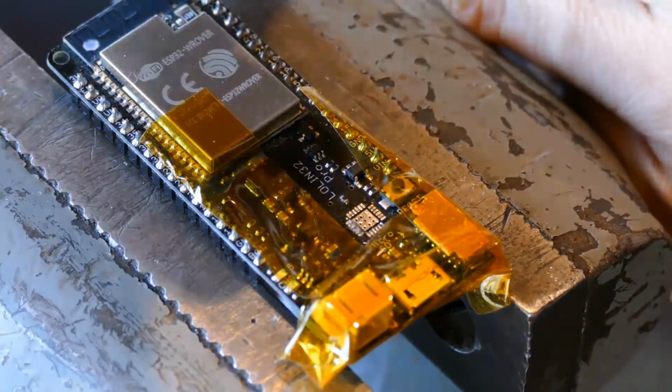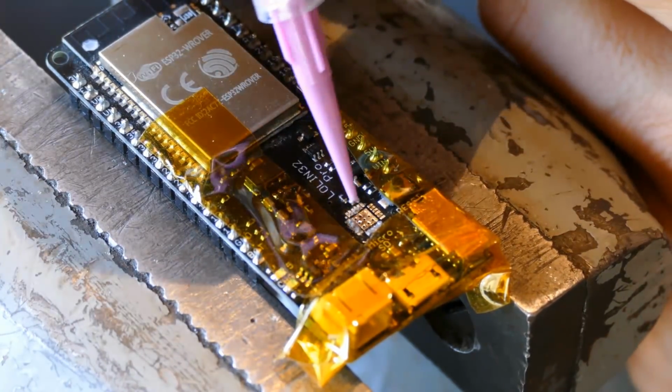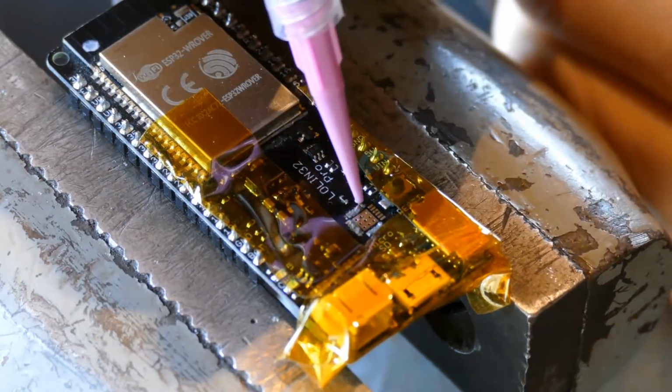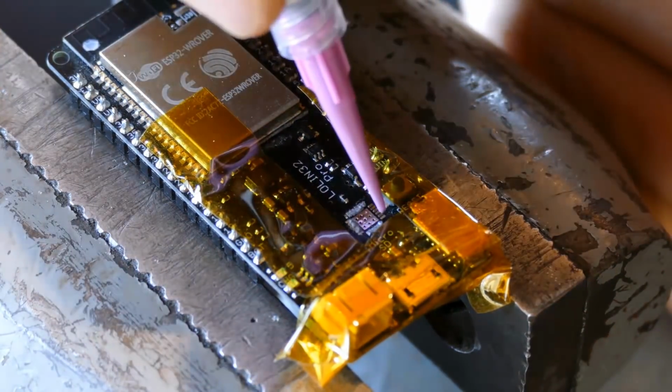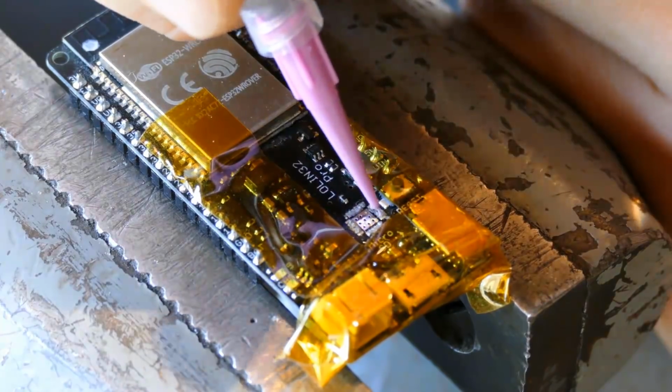This cheap plastic applicator is pretty clumsy. It's very difficult to control the volume. A solder mask would be preferable. I'm applying too much solder paste, but I'd rather err on the sufficient side because I'm pretty sure I can remove the excess with my iron.